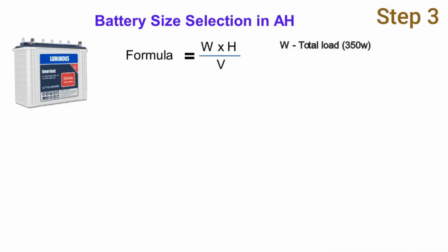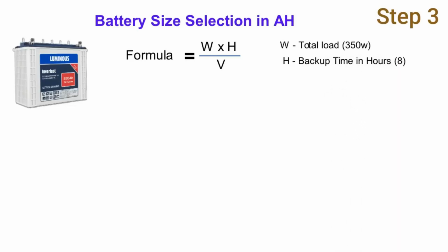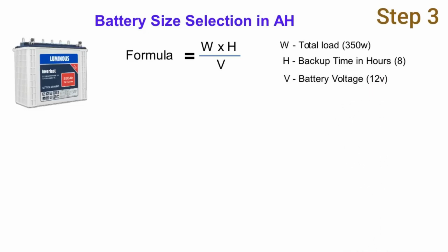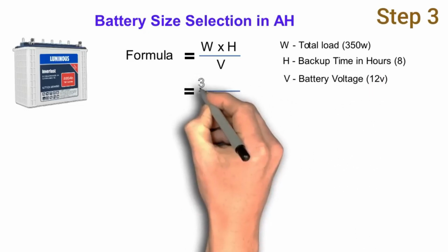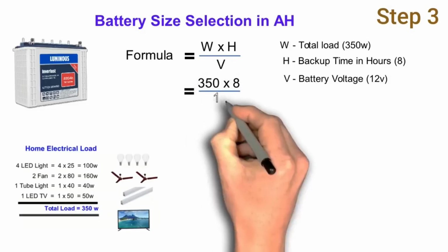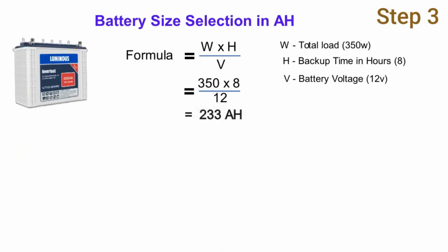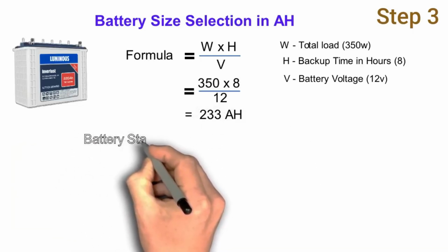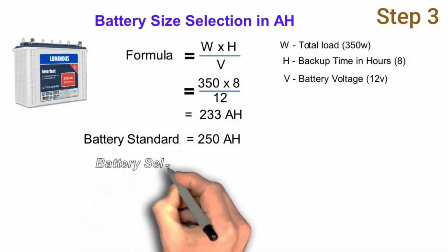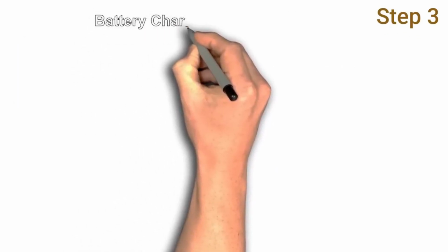Now, we'll calculate the solar panel current. This step is necessary for selecting the correct wiring and ensuring your system is properly set up. To calculate the current, you need to know the voltage rating of the solar panel and use the formula: current equals power in watts divided by voltage in volts. For instance, if your panel is 300 watts and operates at 30 volts, the current will be approximately 10 amps, 300 watts / 30 volts. You'll need to ensure your wiring can handle this current to avoid any safety issues.